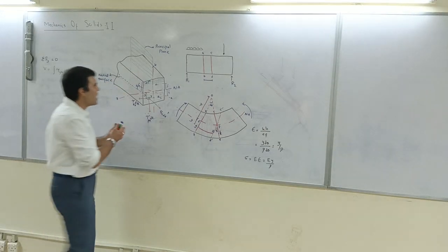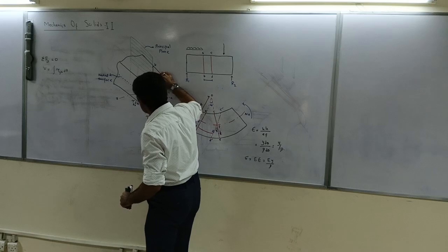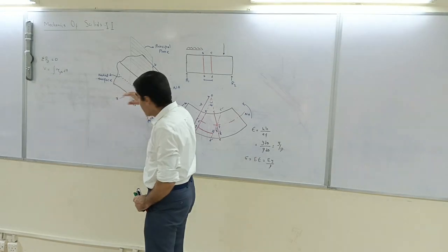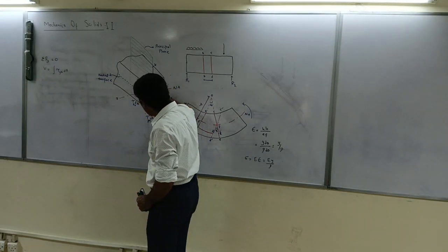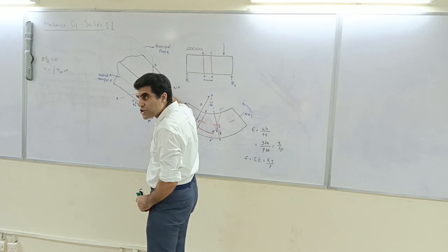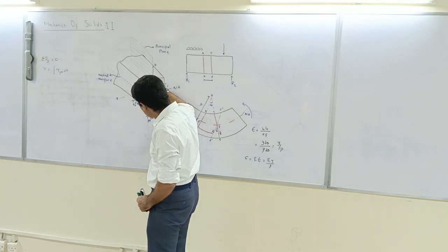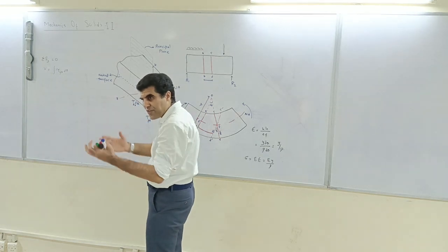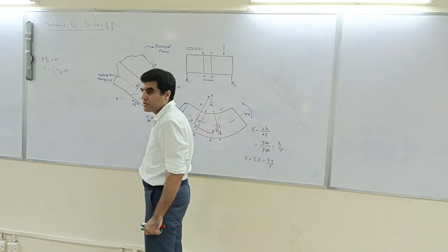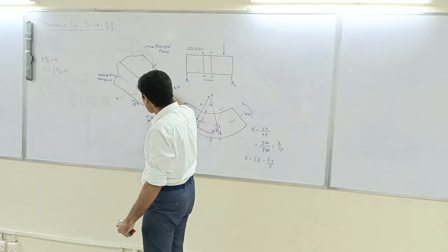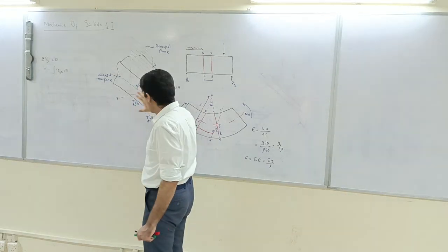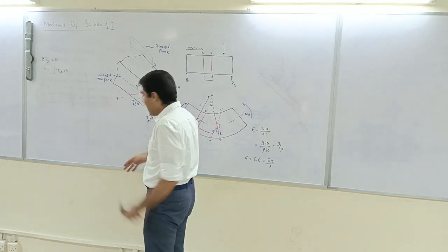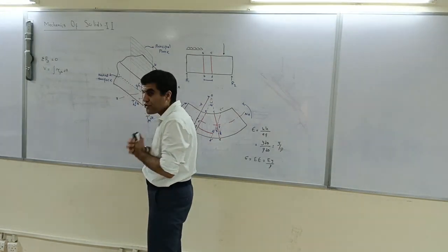So in other words, if I want to find out my shear only in this portion of the area, I will just multiply tau yx, which is the stress, with this area. With just this area, I will get a small portion of shear. And as I go down, the cross section area increases. That cross section will take all my applied load. Do you understand? So this equation tells us how much area is taking the shear force, shear stresses.